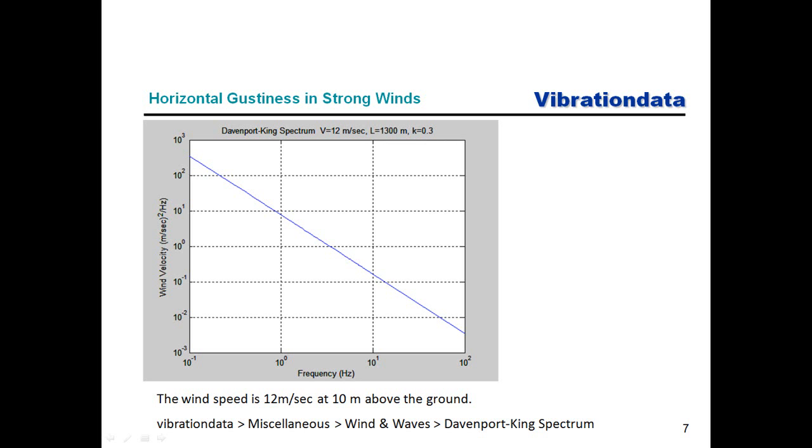Now, if you're working for NASA, think about a launch vehicle. It's like a cantilever beam mounted to the launch stand for some number of days or maybe a week or two prior to launch. And if that launch vehicle was in a place like Vandenberg, California, or the Kennedy Space Center, there's different types of winds that might arise, and we need to consider the possibility of those winds exciting the lateral bending modes of the vehicle.